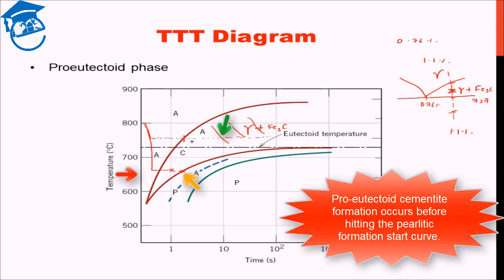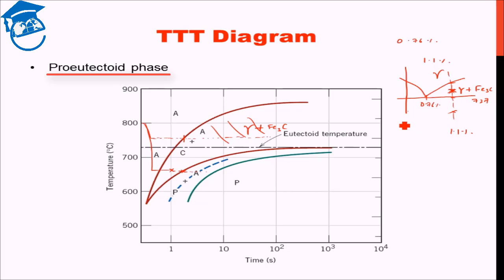This is where the nucleation of pearlite occurs for the first time and pearlite starts to form. Furthermore, it is the same diagram as before. The only difference was that due to the hypereutectoid scenario, we will have the proeutectoid phases formed. This would have been the same if we took a composition over here, let's say 0.5%, then instead of proeutectoid cementite we would have proeutectoid ferrite forming before, but the rest of the phenomena would have been on similar lines.